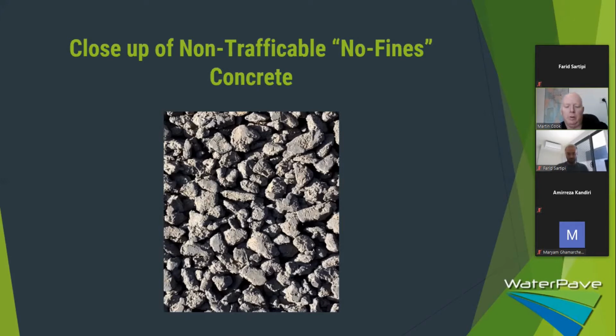So you want to be able to cover it over with some bricks, or a lot of people nowadays use a resin bonded aggregate over the top, which is again porous or permeable to allow the water to go through. They put that in at almost like a 10 or 15 mil layer over the top of the no fines concrete to make it look pretty.